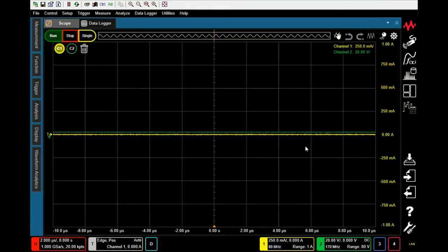Today, this video will show the interface for a CX3324A current device waveform analyzer and measurements using a Bluetooth board that we have. So just a full description here: we have channel 1 connected to a CX1101A current sensor, and channel 2 is connected to a CX1151A passive probe adapter for voltage measurements. So the CX3324A has detected both channels, channel 1 for current and channel 2 for voltage measurements.